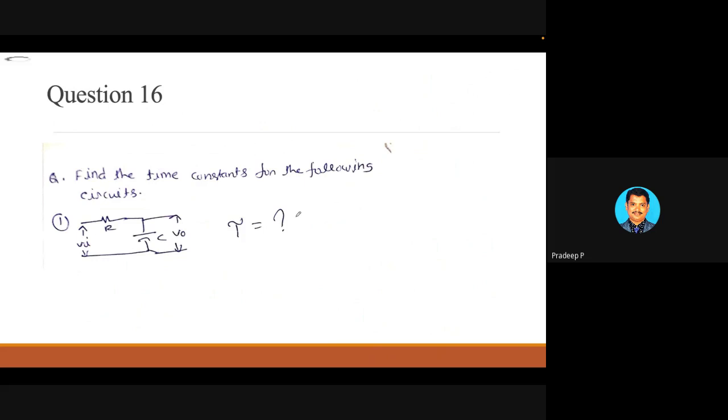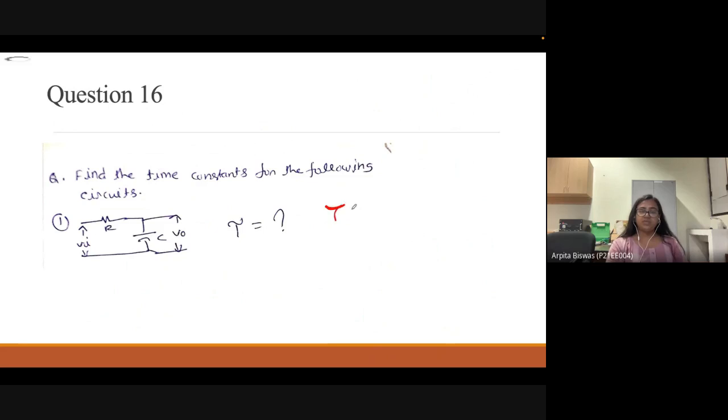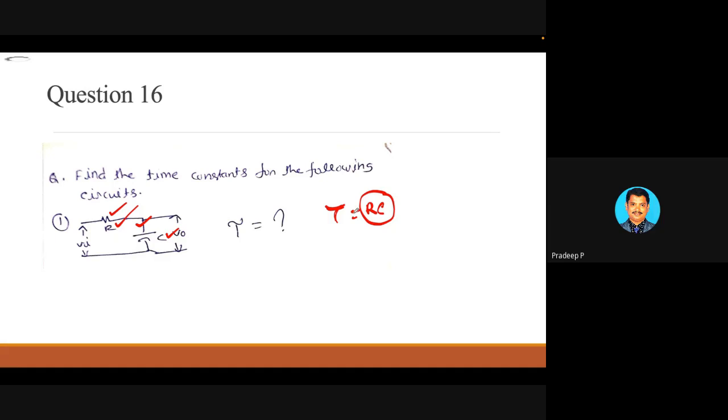The time taken to reach the 60 percentage of the final value we are calculating, 0.693 something. RC is the time constant, madam. Yes, how to find out the equation I am asking about. This is the RC. Okay, so here R and C, all those things are given. So I think this is not that much difficult now. Find out. So if the R value is given and the C value is given, just put down that value here and you can directly find out the tau, the time. Okay. Yes, madam.